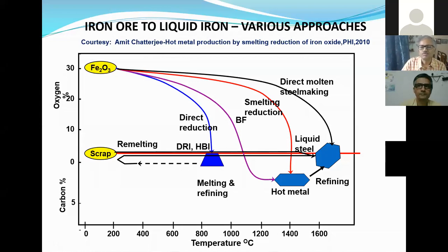You remove all of them, and then your final composition will come here. In this diagram, the carbon composition is shown at maximum less than 1%, and you can find some amount of oxygen is there. Obviously, some residual oxygen will be there. That is also almost at the saturation level because we are producing by charging oxygen. So this is the steel product you can find.